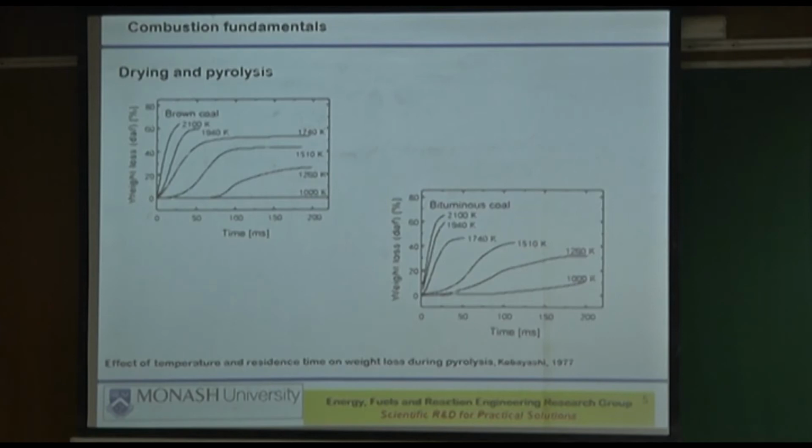There is a difference between some lignites, for example, some have very high ash but low moisture. Some lignites have very low ash but very high moisture. So our brown coal, for example, only has 2% ash when it is fully dried. But when it is not dried, it's got 60% moisture. But it is extremely reactive.